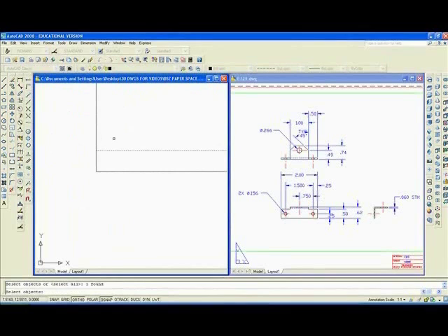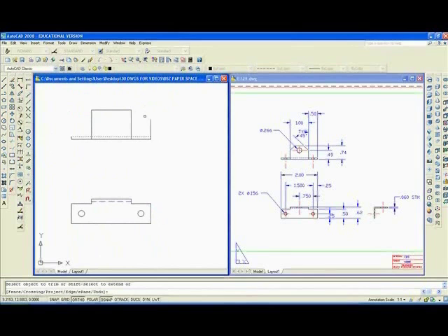Trim. Zoom previous. Trim also that. Now we'll want to draw a chamfer. Well, not really. Well, it's a 45 degrees, so I suppose it could be a chamfer. Let's try it. C-H-A, chamfer.